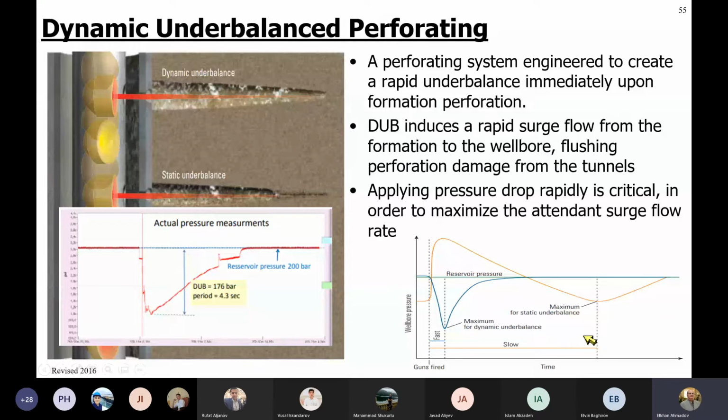This is this green line, okay? So you can see this difference or pressure drawdown. Once we shoot the well, this is the shoot time or guns fired, the explosion creates high pressure and temperature, therefore the pressure goes up. But then when this effect of the explosion goes away, and it's all very quick, you can see it's seconds, it goes up, and then it goes back to the original pressure value, okay?